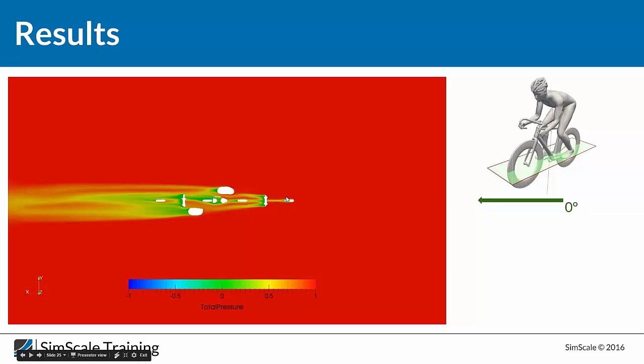But for the large tires, the flow has more space to develop, and that's why we have this transition of the boundary layer from the laminar one to the turbulent one. And we know that in the turbulent one the shear stress is higher, so the flow can stay attached over the side surface and a bit over the back of the tire. Sometimes companies also use a rough surface on the side of the tire, to make sure that you have a turbulent boundary layer, so that the flow is still attached over the tire. Maybe Milad has another comment on this first slide.